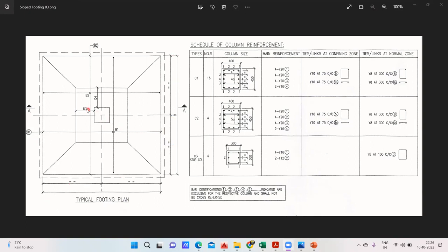Now you may get confused, sir, where we have to take D3. This D3 you have to take parallel to the length side. This is length and this is breadth. Okay, you getting my point? Now my intention is to find this area of the column. This column dimension I know is 400 by 450. So which is 400 in this? The shorter side is 400.